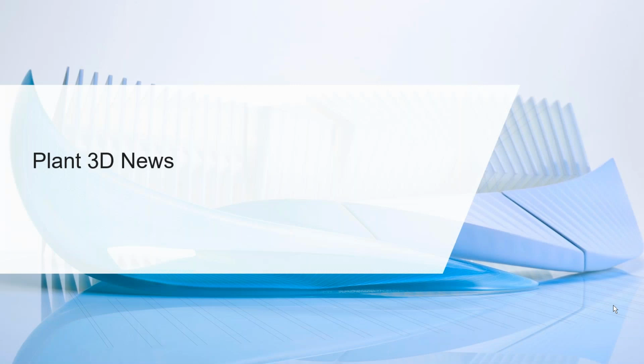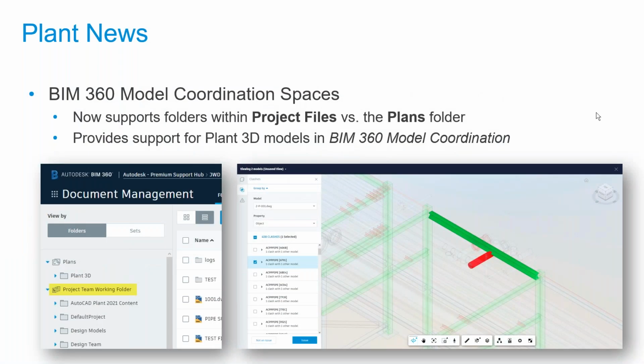So just going into some of the news here, the one thing we wanted to highlight, that we're getting some questions about and looking at, is the new workflows with BIM 360 projects, basically coordination projects on BIM 360. Now you have the option with Plant 2021 of going over to the Docs platform as opposed to Teams before. That opens up some possibilities for using something like BIM 360 Model Coordination, which is a cloud-based method for viewing the drawings that you have in the project and even running some clash detection and things like that. In the past, you were kind of limited on where you could pull those models from.